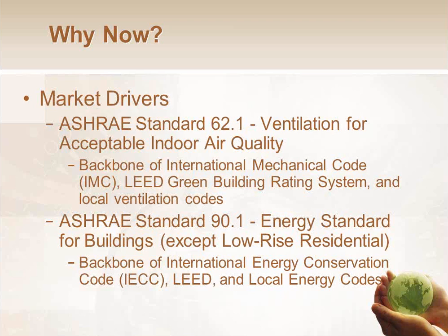So for example, an office building, you have to bring in 5 CFM per person plus 0.06 CFM per square foot. Schools have a similar chart, but it's much higher outside air. Some spaces have less, but there's a chart for each type of building scenario and how much outside air you have to bring in.